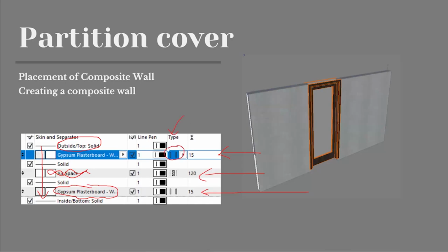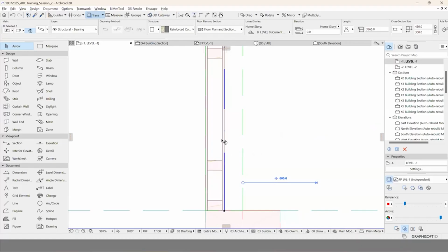Here you will have three options. One would be to tell whether it is a core of the wall, whether it is a finish of the wall, or neither of them. We call it other in ARCHICAD. For some reason, that is a name that is being given. So these are the ways we give a type. Similar with thickness, which line you have to take, but the line type we will be addressing in the coming session. And this is the layer separation. So like this, we are going to create one. So that would be the first attribute.